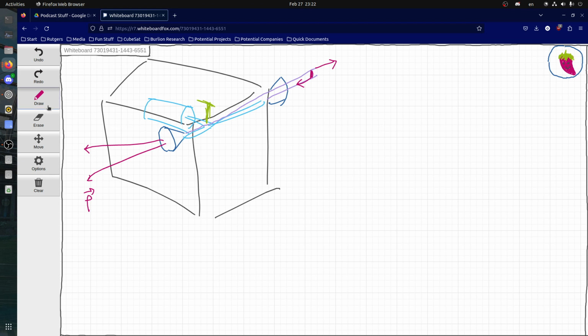So with thrusters, usually something you have to think about is the error in the design of the mechanical tolerance, you could say. These also have very good accuracy, usually on the order of 1 degree, but the control algorithms that have to be developed have to be much more tuned and better, and you have to account for the error much more carefully. A major drawback to these is the finite amount of gas that you have, because you can only expend this momentum while you have gas, right?